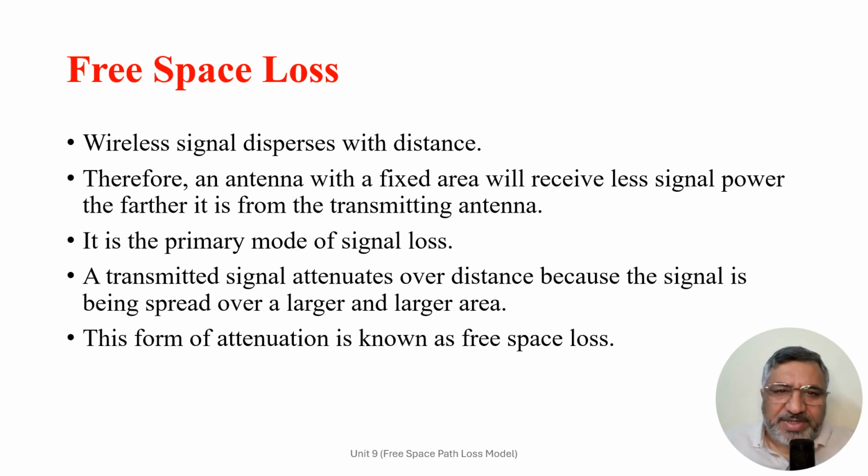This form of attenuation is known as free space loss, which can be expressed in terms of the ratio of radiated power to the power received by the antenna. And generally, it is expressed in decibels, which is just by taking 10 times the log of the ratio.